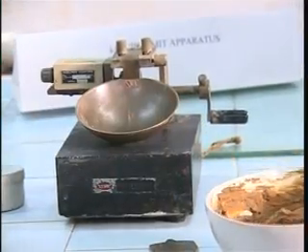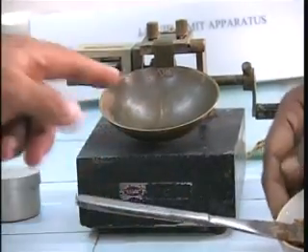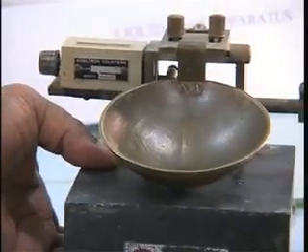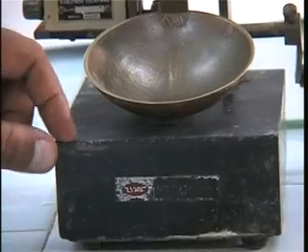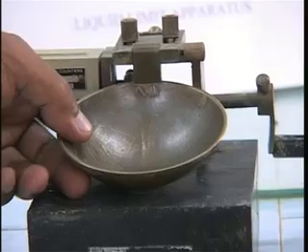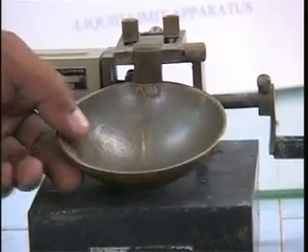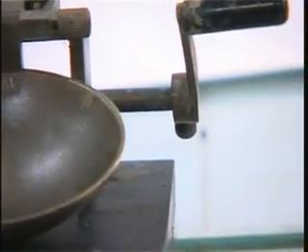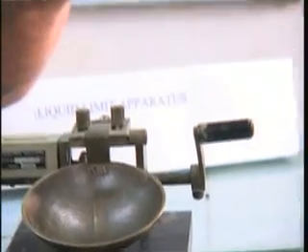We are going to make a pat of this soil sample in this pan here. This is the Casagrande apparatus, which includes a hard black rubber base, and it has a brass pan. This pan is of standard dimension, and it has a certain standard fall, so it goes up when it is cranked up using this handle. It goes up a standard amount of height, and that height is given by this dimension here.